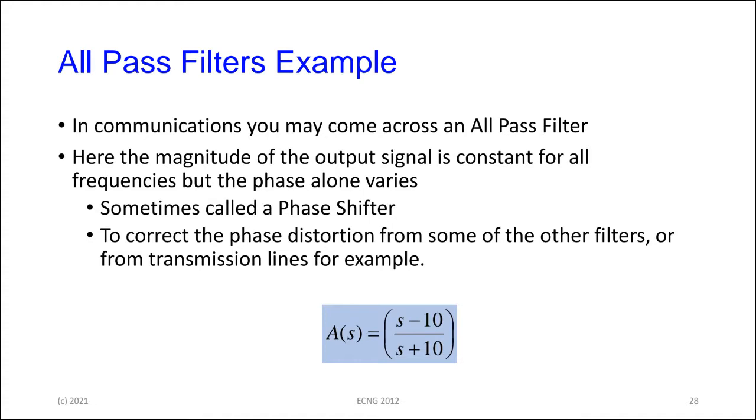A transmission line, which carries high frequency signals, has capacitive, resistive, and inductive behavior going down the road. So it acts like a very complicated passive filter. So there's amplitude distortion and there's phase distortion around the place. These all-pass filters, if properly designed, can correct the phase change that another filter would have created, to get you back to a situation that you wanted to be in before.